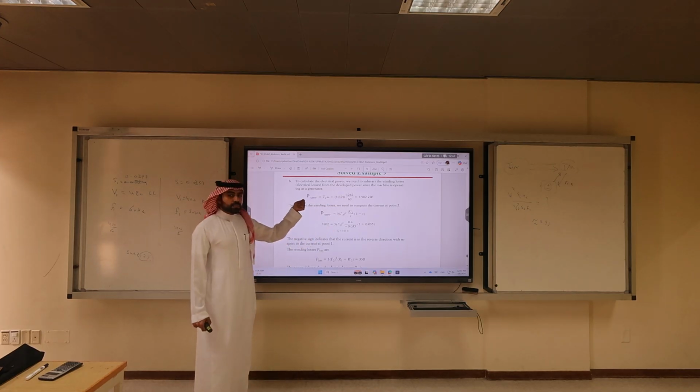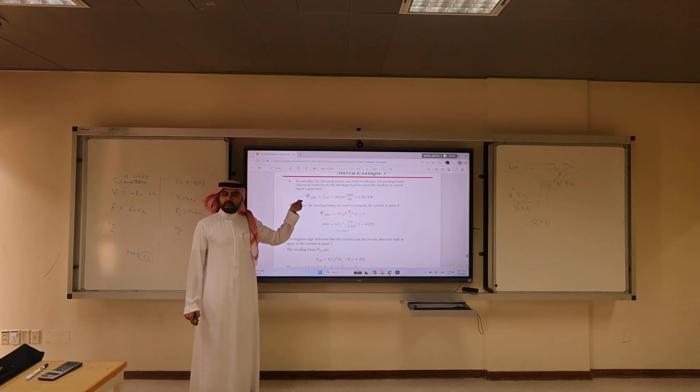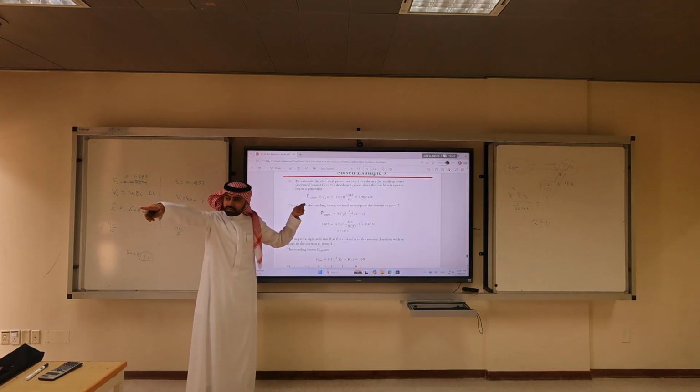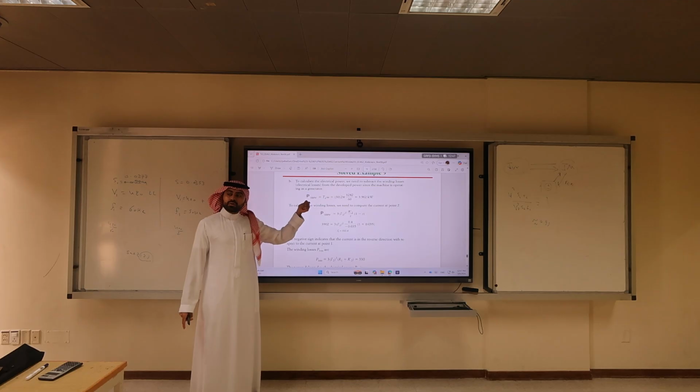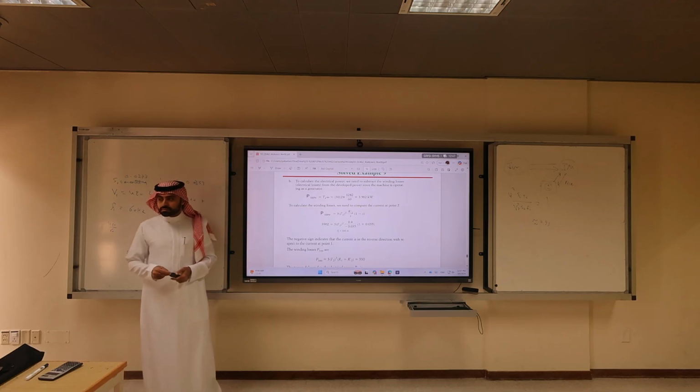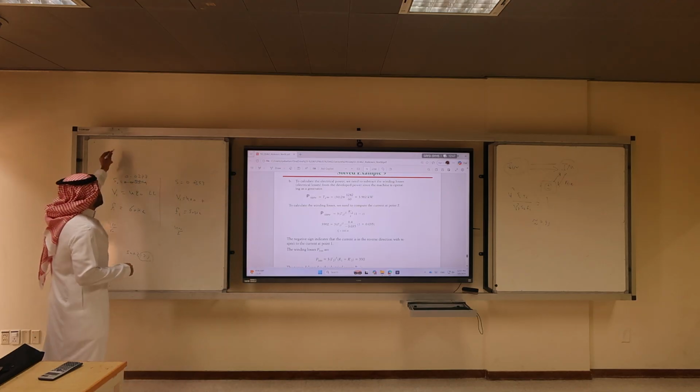So what is the developed power? It is the converted power. Osama asked me on Teams, he said there is a mistake in one of the slides. When we talk about the maximum torque, we do not look at converted, we look at the air gap power. The mistake was that it used synchronous speed where it should use the actual speed.